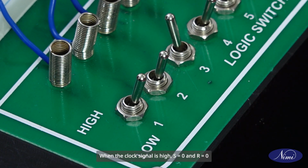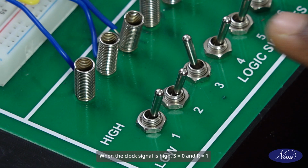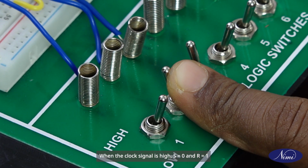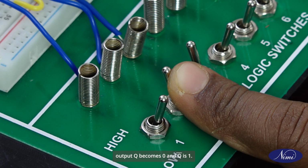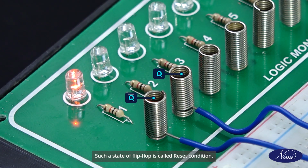When the clock signal is high, S is equal to 0 and R is equal to 0, output Q and Q bar remain in their previous states. When the clock signal is high, S is equal to 0 and R is equal to 1, output Q becomes 0 and Q bar is 1. Such a state of flip-flop is called reset condition.